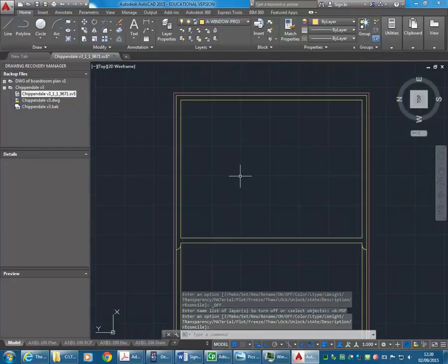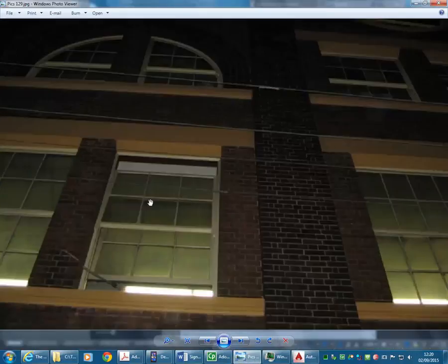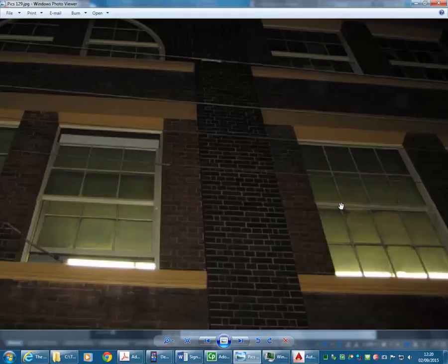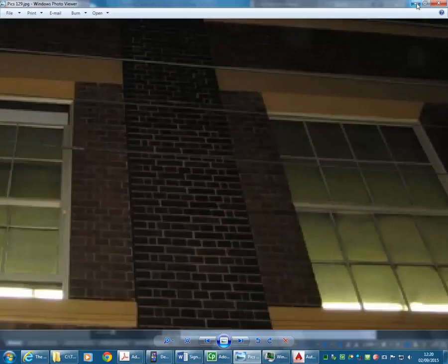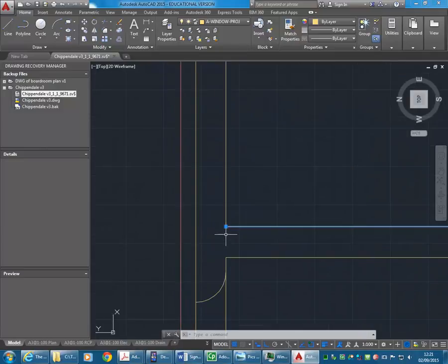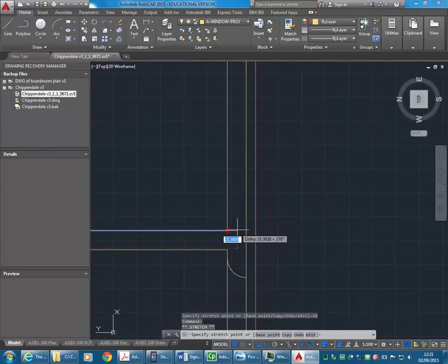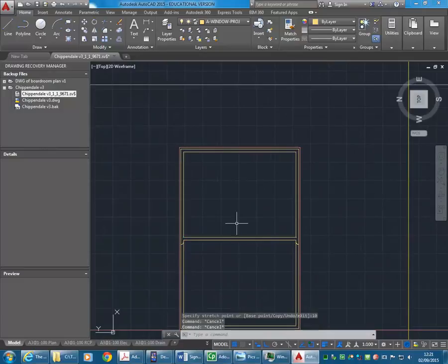So again, following the same approach, you can draw in the glazing bars if you just guesstimate the thickness. So we'll say they're, well, in reality probably about 10 or 15 mil, but let's make them 20. And so to set that out, again, just think about the centre lines. Now, to do this properly, we need to extend that line across 10 mil, and on the other end as well. I'm going to take it back afterwards, but you'll see why in a second.